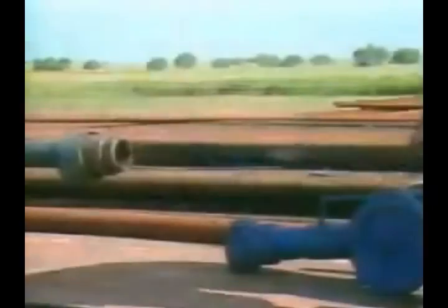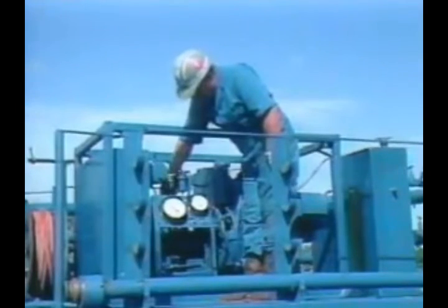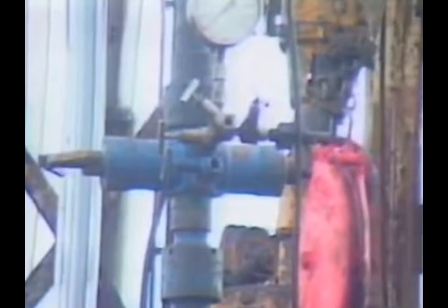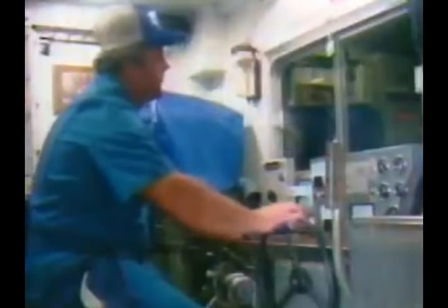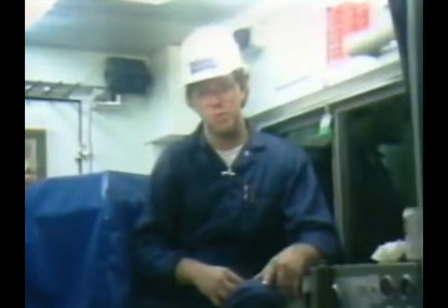The gun assembly is introduced into the riser and the pressure control assembly is sealed. A grease seal is established in the flow tube. The blowout preventers or Christmas tree swab valve can now be opened when the gun assembly is ready to be run into the well. Now, in order for the guns to be positioned correctly across from the intervals we wish to perforate, we need to correlate the casing collars measured by the gun assembly with those on the PDC log.